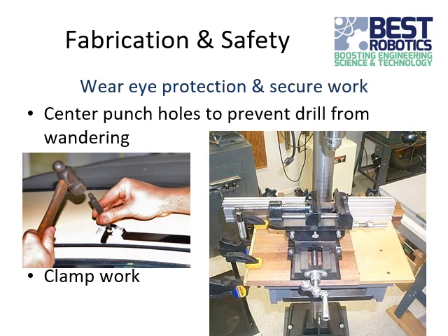Center punches are really cheap. You can get spring-loaded ones or ones you just hit with a hammer. You can sometimes get away with just using a nail or something like that, but it's a good idea to have an actual center punch. And you want to make sure you just give it one good clean whack.